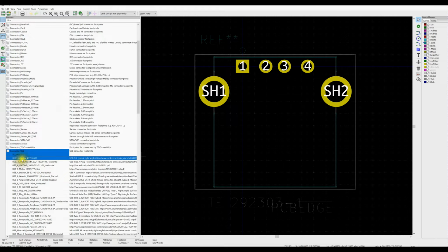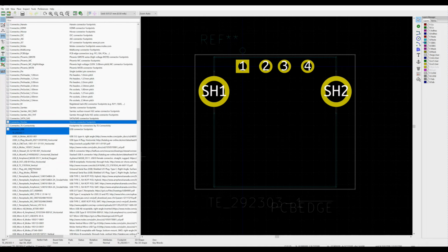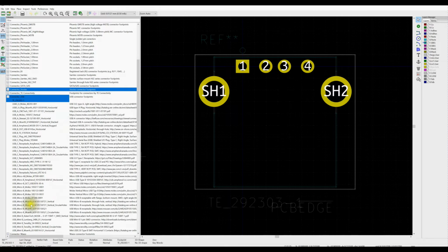And we can see what's happened here is, let's see if I can actually get the highlighting to change. I can't. So it's in the connector USBs, and the name on it happens to be that part number from Digikey. It's actually the manufacturer's part number. I've fought with renaming these. Part of me likes the fact that that is the manufacturer's part number, but it means you need to kind of keep track of that.